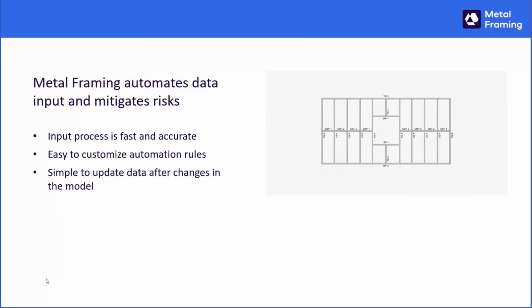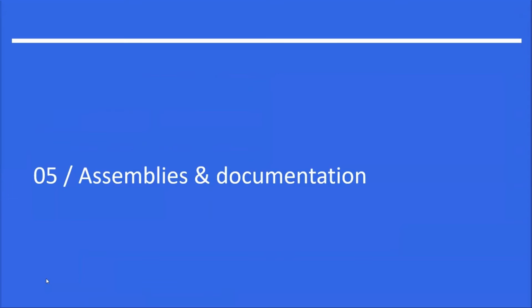Also, it's simple to update data after changes in the model. Let's say you reframe your walls, or you add new frames. You just simply click frame. You just simply click number walls or number elements, and all those changes will be updated. Now, assemblies and documentation.